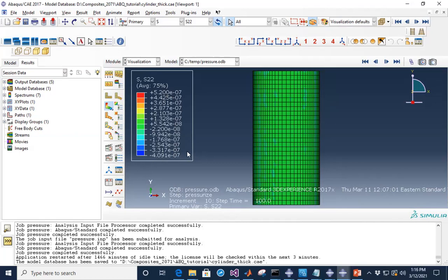And remember the pressures that we applied in SI units are of the order of 1e6 Pascal. So the stresses in the vertical direction in these contours are about 12 orders of magnitude smaller. These are just numerical perturbations, and effectively the stresses in the vertical direction are 0,